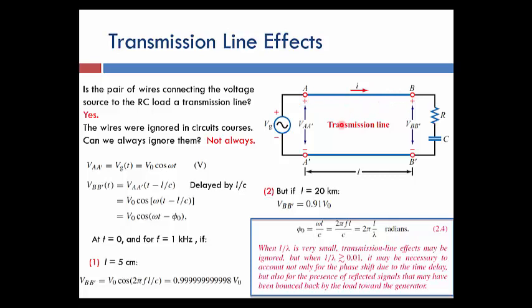Previously we worked with electric signals oscillating at very low frequency. Its frequency may not exceed 60 hertz, and according to that it has a very long wavelength. So by comparing its wavelength to the length of the transmission line or the wire, this length could be neglected compared with the wavelength.